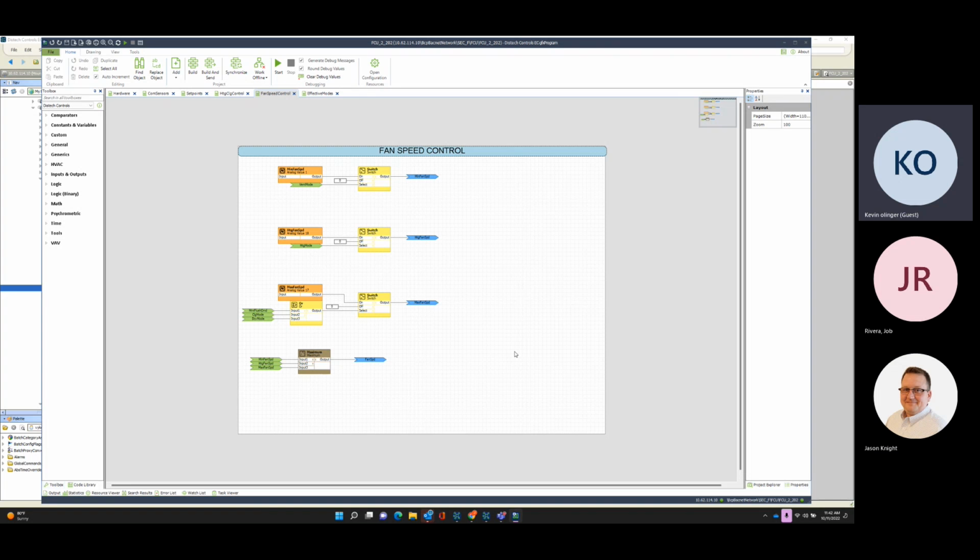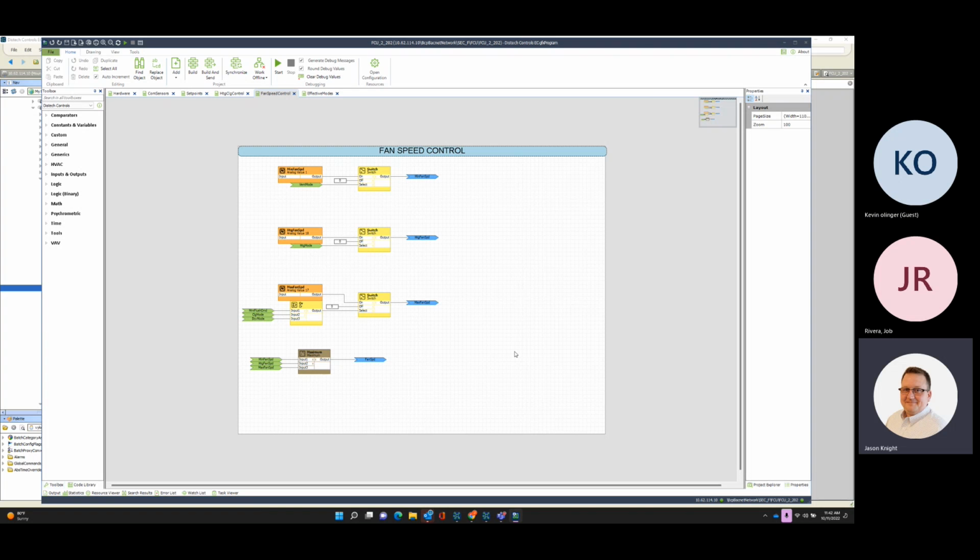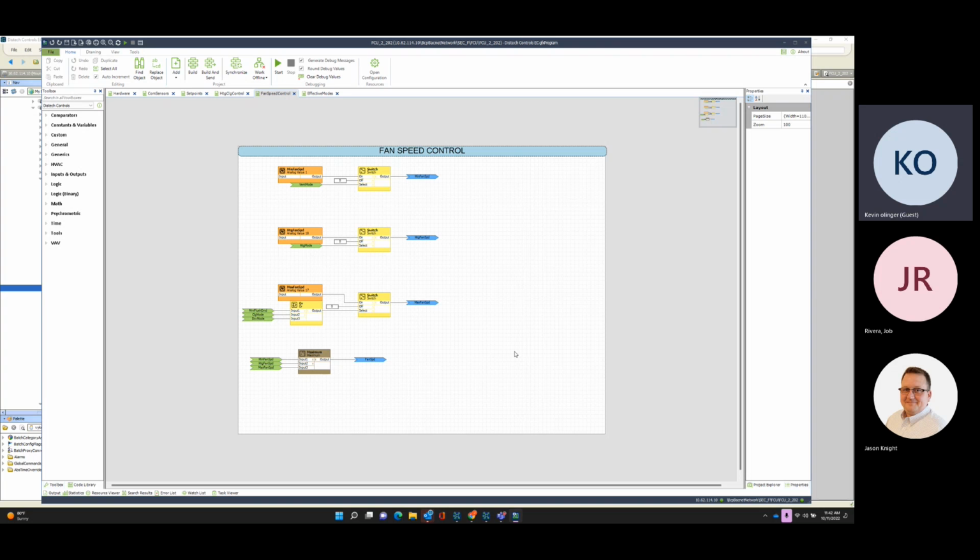Yep. And then are we only monitoring one motor when you say that we got one status, or is it fair to say if either status goes? No, you're monitoring the fan wall when there's multiple motors. So in my mind the question is series or parallel.